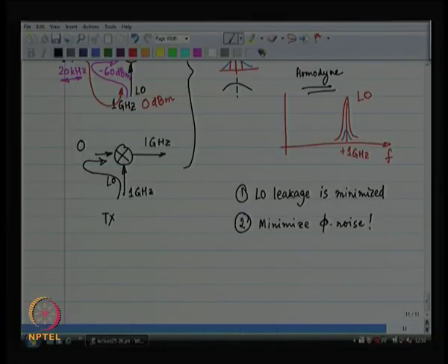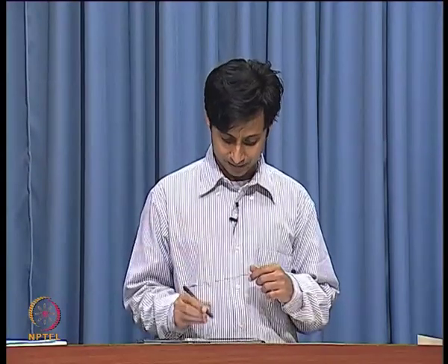What about in the transmit case? Same story. Local oscillator leaking into the DC. When the local oscillator leaks into the DC, I get the square of the local oscillator with some attenuation. Now, remember that the local oscillator is not a perfect signal. There is phase noise associated with it, and when there is phase noise associated with it, I will get the square of the phase noise on top of the DC. Is this a problem? What does the output spectrum look like?